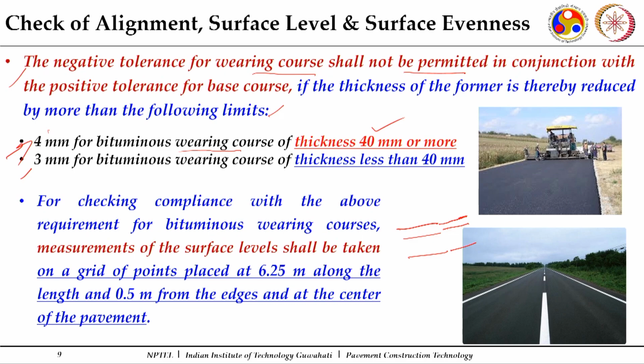And see, this is the paving operation which is going on. Once the paving operation is done, as soon as the compaction goes on, I can make some checks for the loose thickness also, and as soon as the section gets compacted I can immediately proceed with checks at some random places, so that if there is some fault I am able to figure it out and get it rectified before more length is constructed.